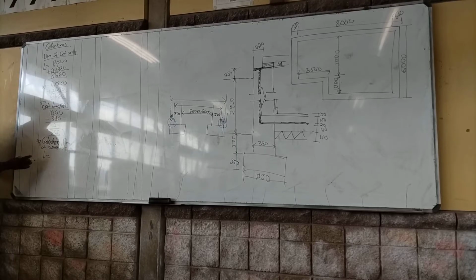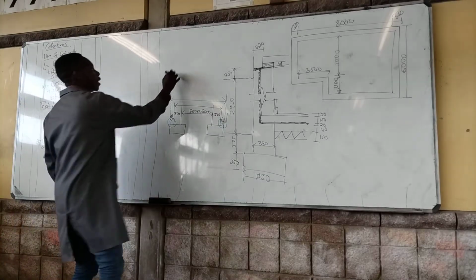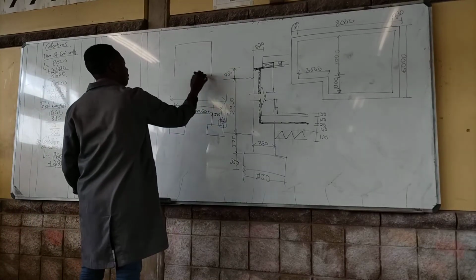We know the length of the wall externally. So we know the backfilling. For the external backfilling, we're going to take the external length and add it with 2 by 335. Does it make sense? So here it is. We are given, let's focus on the plan view.